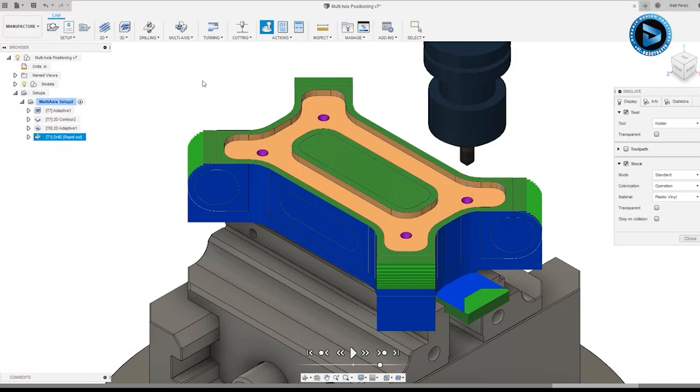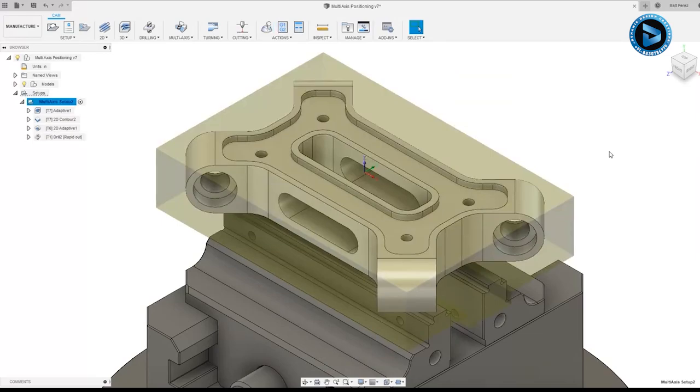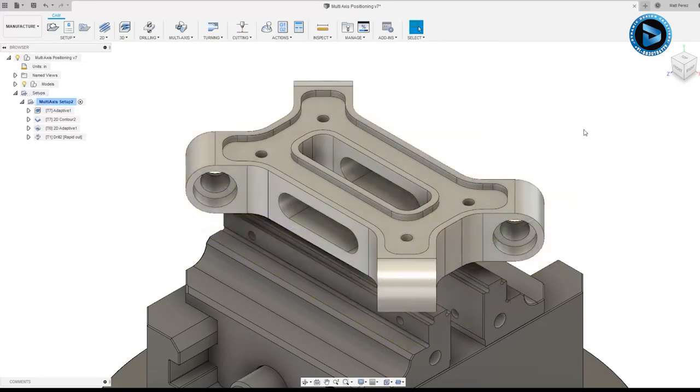Now, if we want to go a little bit past what the 0.201 is, that would be okay because it might actually help the tap start if we're using a thread cutting style tap rather than a roll tap that's going to be forming threads. Again, all these decisions need to be based on your specific geometry, your tools, your design intent.